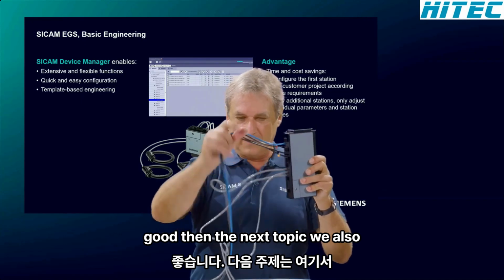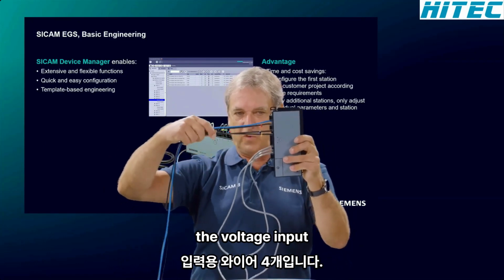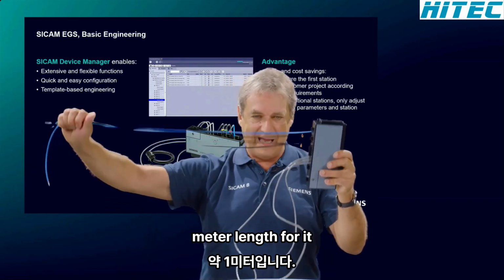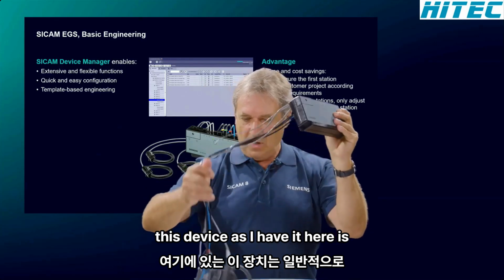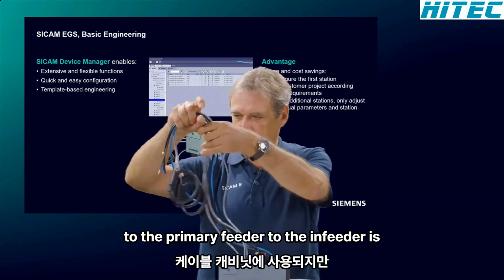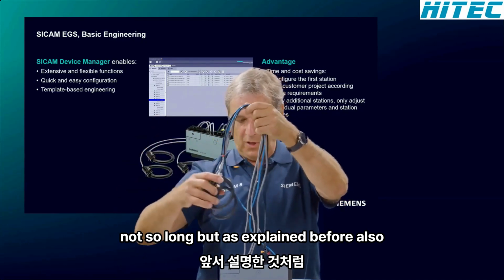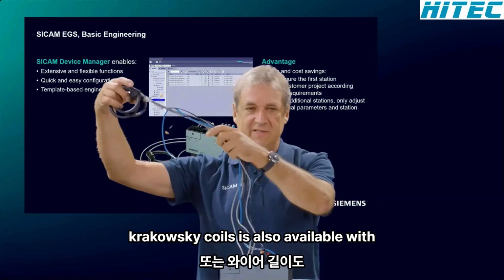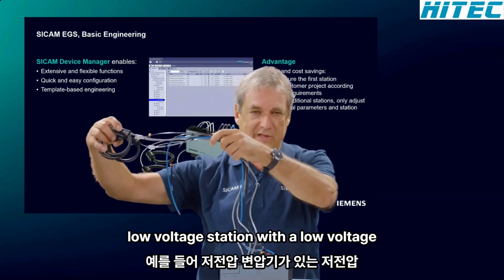Good. Then the next topic, we also explained it. Here are the 4 wires for the voltage input. As you can see, it's approximately 1 meter length. This device, as I have it here, is normally used for cable cabinets where the distance to the primary feeder or to the in-feeder is not so long. But as explained before, this wire length to the Rogowski coils is also available with 3 meters, especially if you have, for instance, a low voltage station with a low voltage transformer.